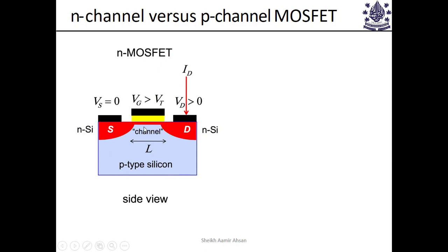Okay, and how the channel is formed is called the field effect, and so it depends on whether we have applied a strong VGS, or strong gate to source voltage, which is greater than the threshold voltage. In that case the channel gets inverted and we have a current. So we'll talk about all of this MOSFET operation in really thorough detail. For now you'll just have to bear with me because I'm just introducing this topic.